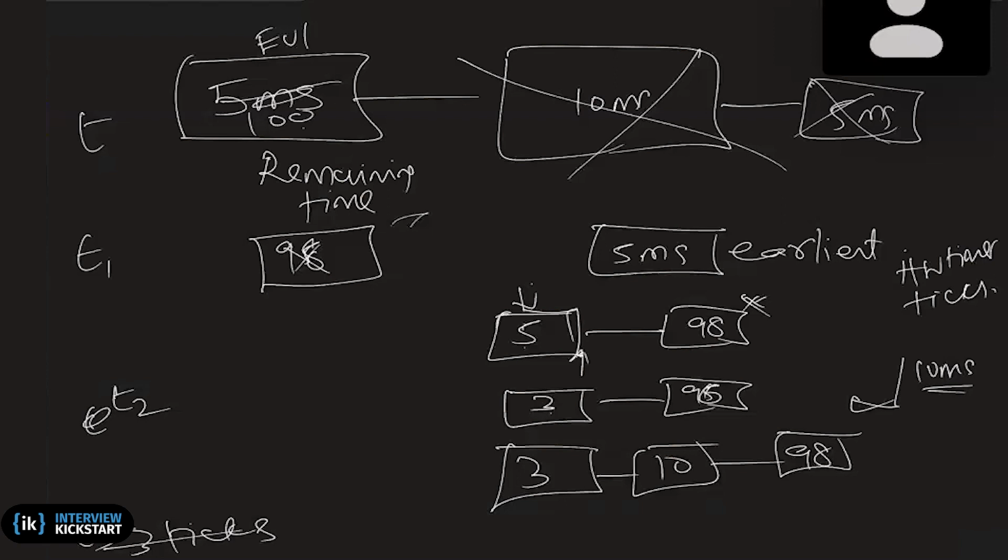Let us see, at that time when it expires, it will track this and then reprogram it. Let's say when this expires, it becomes 93, right? This is 98 minus 5. So 93 ticks are remaining. So it will reprogram the timer counter with 93. Then one more timer came, 10 millisecond. So the 93 will be stopped and a 10 millisecond timeout will be programmed, and this will be adjusted to 83. That's the way it works.